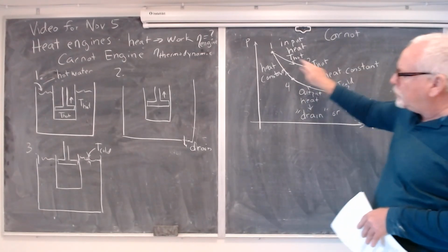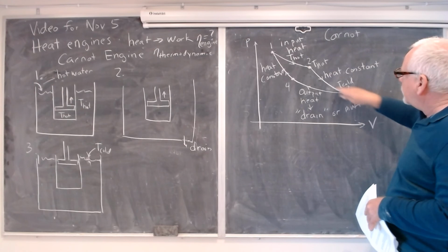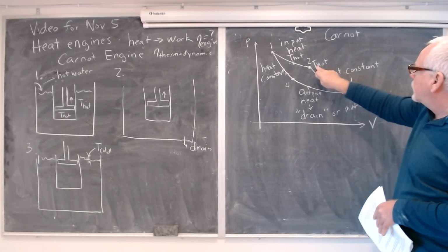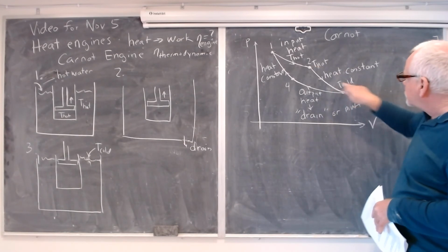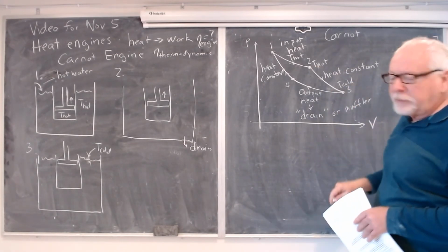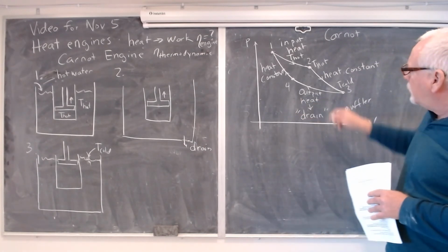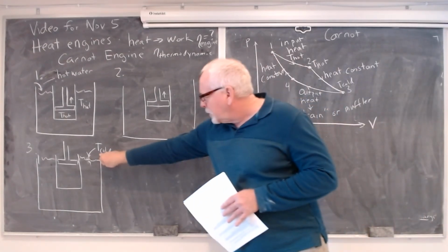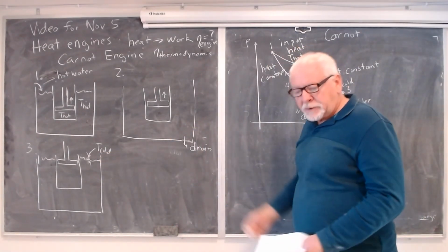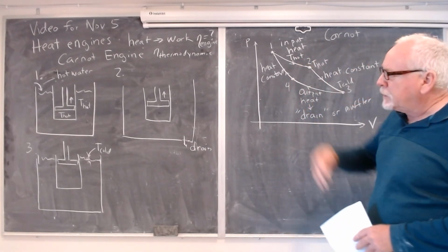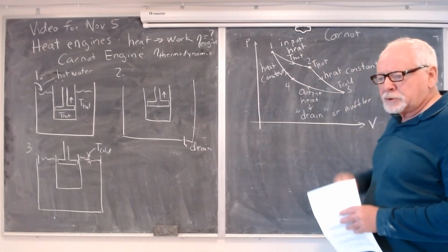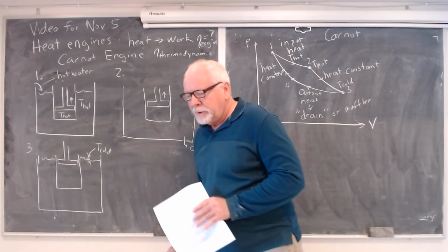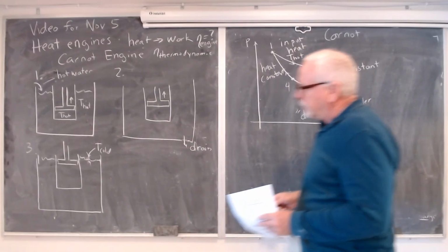And then at step 2, we drain the water. If the piston continues to go up, the gas expands, and because an expanding gas cools, it goes down in temperature, and it goes down to T cold. Now you may be starting to think, how did we know that it went down to T cold in that step, right down to the temperature of our cold water? Well, because we've designed it that way. We've designed this thing with some kind of computer that is controlling where the piston is at a maximum, minimum, etc., so that everything fits together.